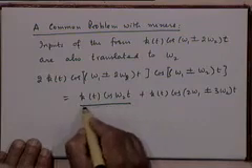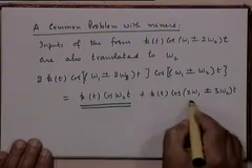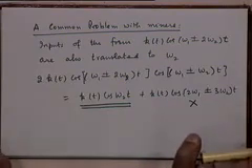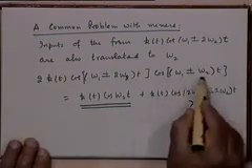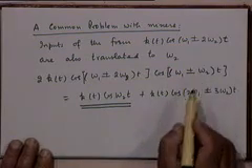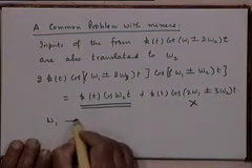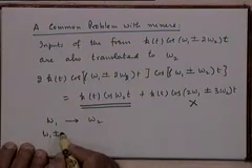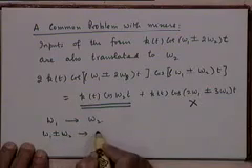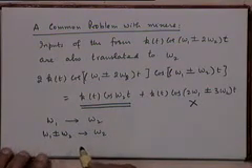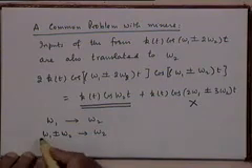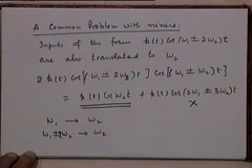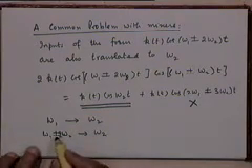And this will again show up at the output of the same band pass filter. This will get eliminated, right? This is the point I was making. So when you use a local oscillator of this frequency, basically what you are saying is omega 1 will go to omega 2, and omega 1 plus minus 2 omega 2 will also go to omega 2, right? And of course the sign will be the same.